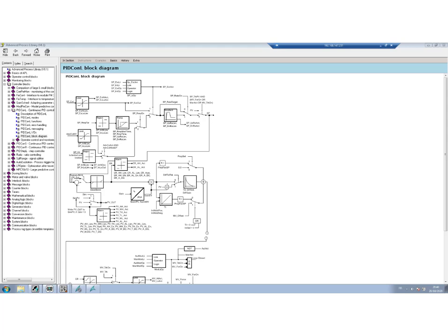Well, normally this is setpoint minus PV, and then you go through the deadband and you have the error after the deadband, and you can then use limits to generate alarms, as I have shown you before. So here you have the multiplication by the gain, but you also have the possibility here to work in a normalized fashion, right? So now here we have the normalized error.